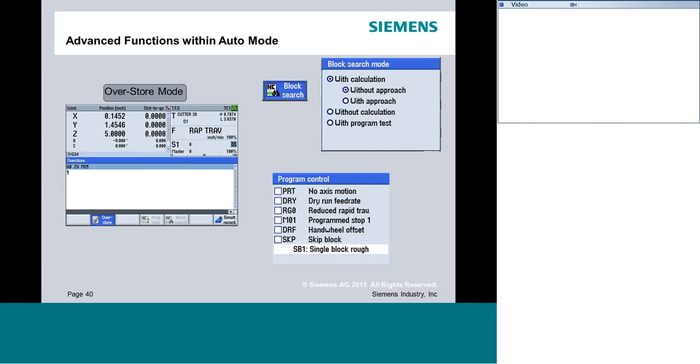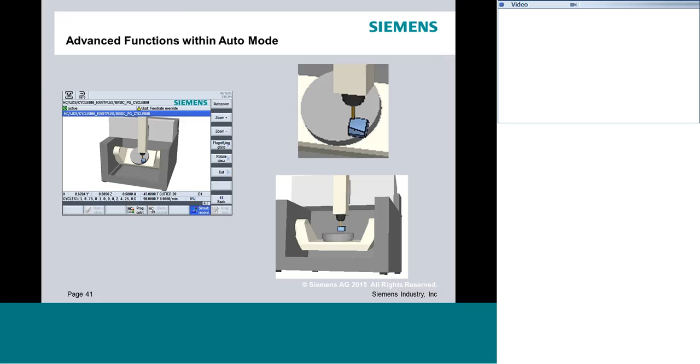All three of those are very handy, especially on some of these 5-axis machines, because they go at very high rates of speed, especially these rotaries. And a lot of times I don't want to run anything if there's potentially an over-travel issue. So we'll explain that more in a second here. We're also going to talk about the beauty of how this is now completely independent of wherever I stage my part. So we'll move some zeros around, and you'll see that the program will dynamically adjust for it, and it's going to handle it however it needs to without me having to change the part program at all.